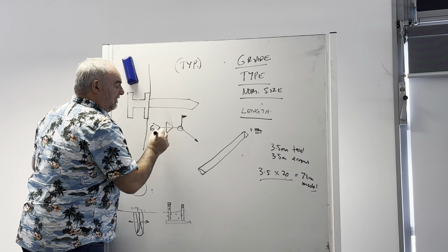Is that in the 3602 standards? Would it be under concrete or steel? It's in the notes, and I also talked about it on the video. You ignore the H in terms of the fact that it's not a distance to the H, it's a distance to the edge of the plate.